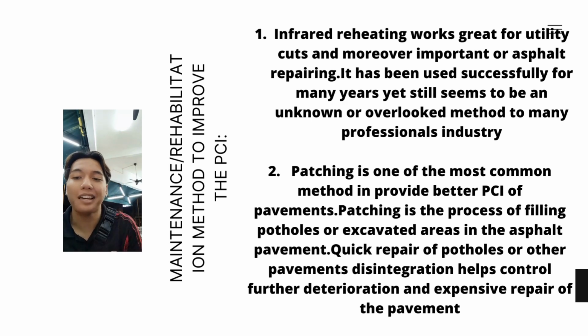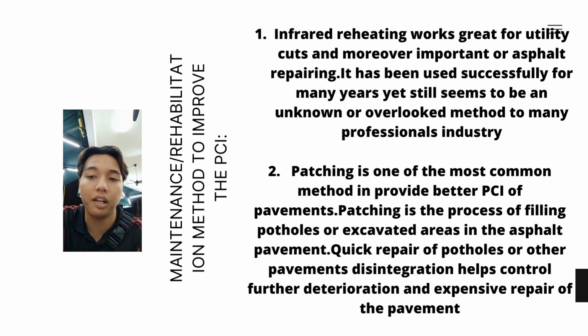Warahmatullahi wabarakatuh. My name is Kennedy and I'm going to discuss the maintenance and rehabilitation methods to improve the PCI. The first method is infrared reheating, great for utility cuts and moreover important for asphalt repairing. It has been used successfully for many years, yet still seems to be an unknown or overlooked method to many professionals in the industry. Second, patching. Patching is one of the most common methods and provides better PCI for pavement. Patching is the process of filling potholes or excavated areas in the asphalt pavement. It is a quick repair of potholes or other pavement defects. This helps control further deterioration and expensive repair of the pavement. That's all from me. Thank you.